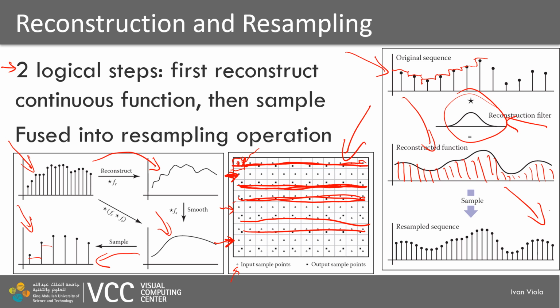And what we can see here is that here is one reconstruction, here is one convolution from the samples happening, here is another convolution from the samples happening, and we know that based on the associative rule in convolution, we can actually convolve these two filters together and perform the reconstruction and band limiting for our output sampling in one pass.